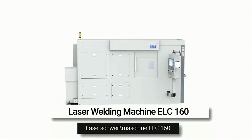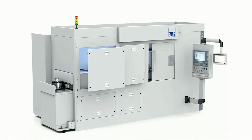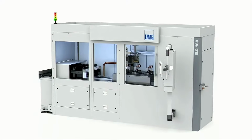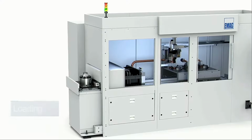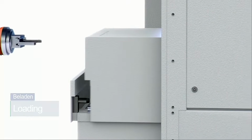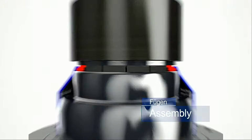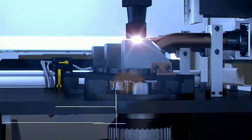So either we have the possibility to implement a robot cell or a gantry, or also manually loaded. And if we start first of all, on the left side there is the chuck and the slide, which is NC controlled, moving underneath the different functions. So we first of all start with loading the two single components, and to make sure that the two single components are in the right position, we first of all press the parts together. Important to mention is that the chuck underneath is not losing the fit during the whole process. So we are always able to hold the very right position. So we first of all have assembled the workpieces, and then we start with the welding operation.